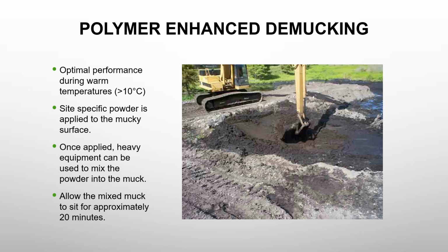And so what we can do is, when we've dewatered a basin and we have very high water content sediments that are soupy and difficult and expensive to manage and remove, maybe we're cleaning out sediment basins, you can apply the granular form. Again, it's site tested. We still do a sample analysis to make sure it reacts and works, but we can apply it to the sediments, mix them in as they're doing right here, and allow them to sit for about 20 minutes.